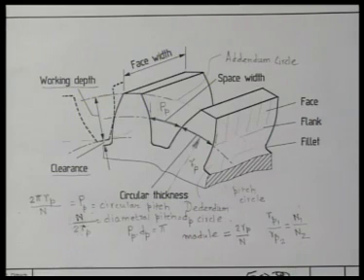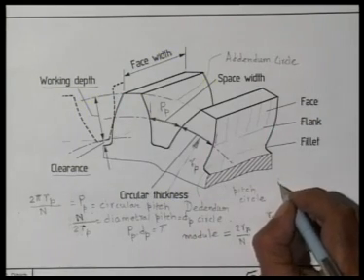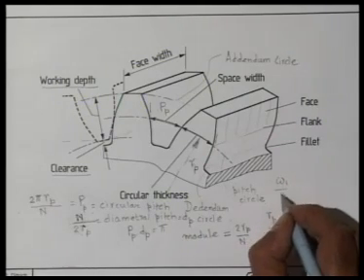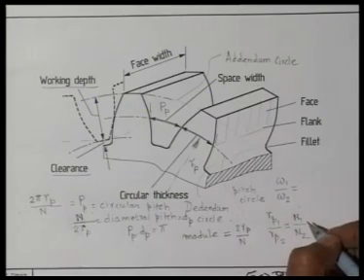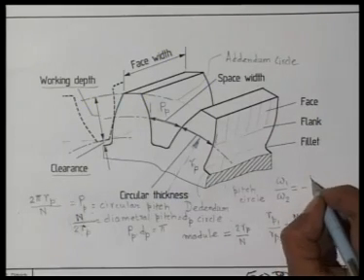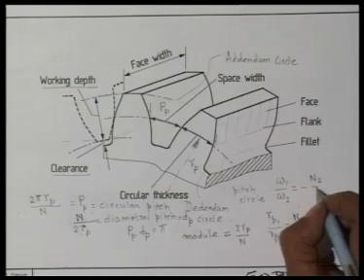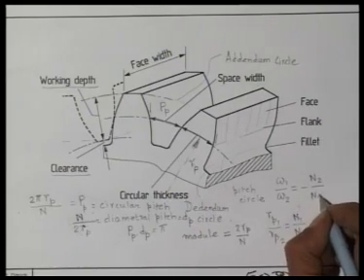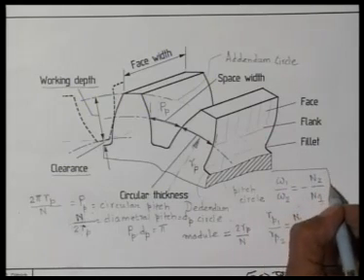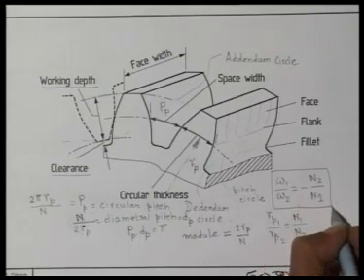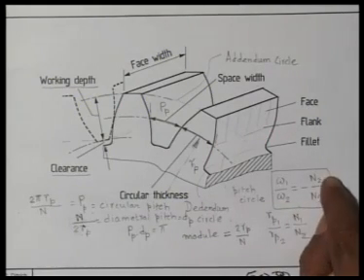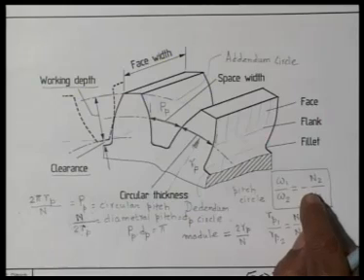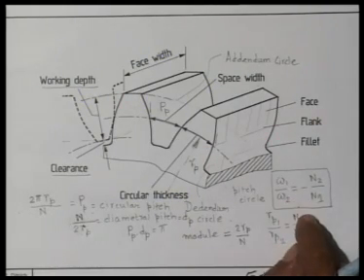We have already seen the angular velocity ratio omega 1 by omega 2 was minus Rp2 by Rp1, which means minus n2 by n1 for a pair of external gears. So the angular velocity ratio is inversely proportional to the number of teeth in the gear, with a negative sign for external gearing and with a positive sign for internal gearing.